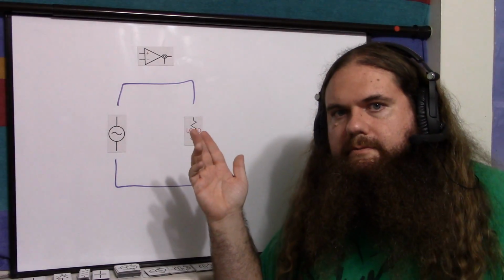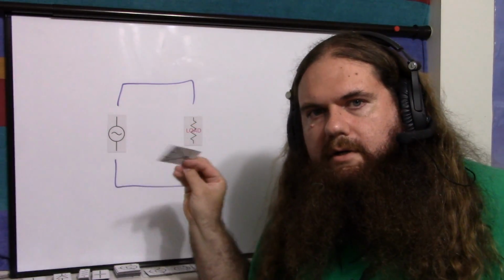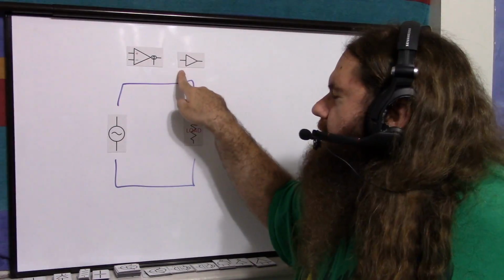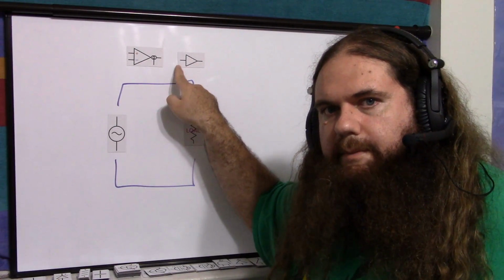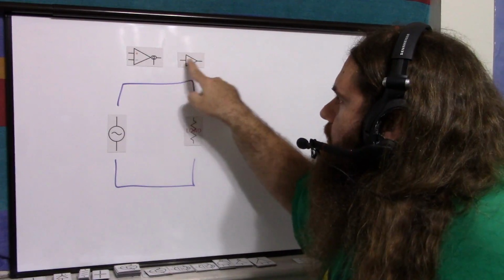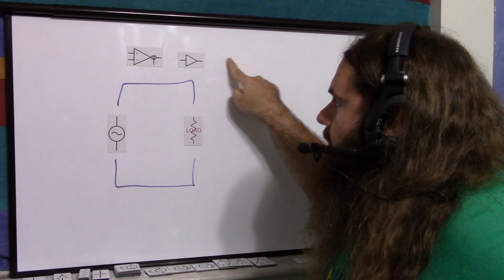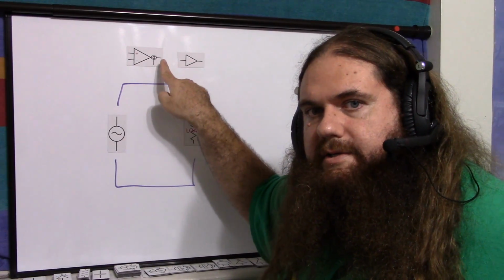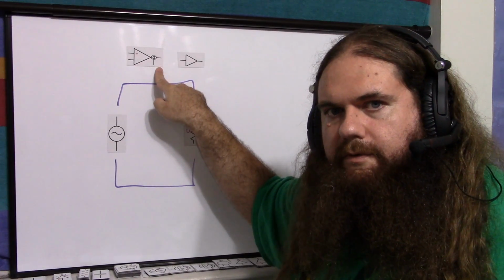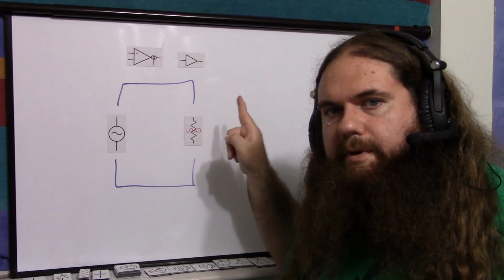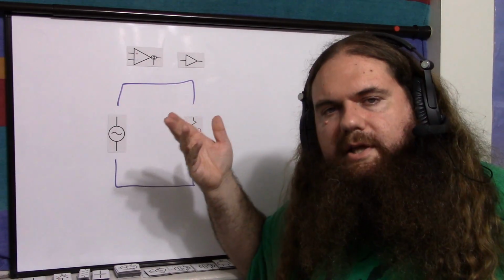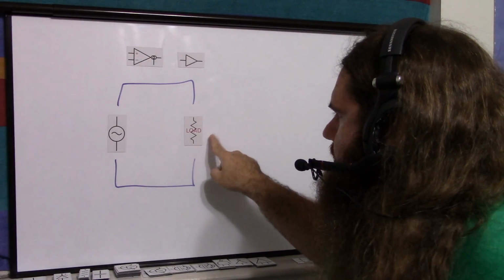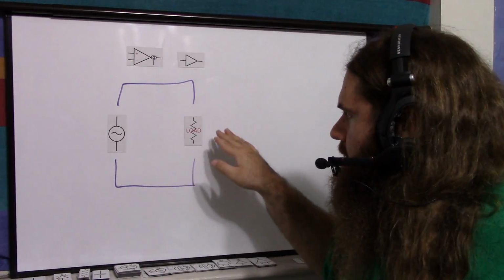So it's the same principle. That's why the OTA is called unbuffered, and if you add a buffer, then it becomes a voltage source, because if you add a buffer, then the impedance is going to be the same every time. It's going to be a high impedance input to the buffer. So whether you hook up a speaker or a microcontroller pin or whatever, the input of the buffer is going to have the same impedance, so it'll be the same signal every time, because same impedance, same current equals same voltage, and then it doesn't matter how much power is drawn through the buffer because it's using the same input voltage. So that's why a buffer turns an OTA into an op-amp, other than how you set the gain. So that's another thing about the constant current source, is your load matters.